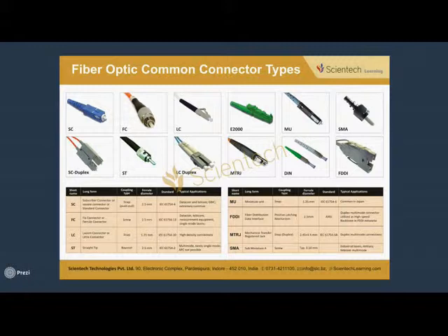The ST connector is round and uses a push and twist connection similar to BNC. The SC connector is square, and uses retaining clips to hold its position. Sometimes two SC or ST connectors are fabricated into a single unit and generally referred to as duplex connectors, which means the single connector is referred to as simplex. The FC connector is designed with screw threads as part of the physical design. They're very similar in design to coaxial screw-on connectors.